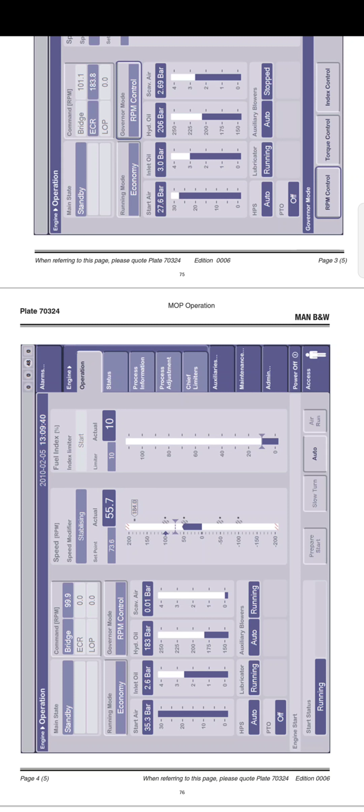And there is the auto button. The auto button is pressed when start preparations are completed and the engine has to be started. So after the start preparation, everything is completed, you are satisfied with your preparation, then only you press this auto button. Engine is ready in all aspects. When selected, the engine will perform a normal automatic start.